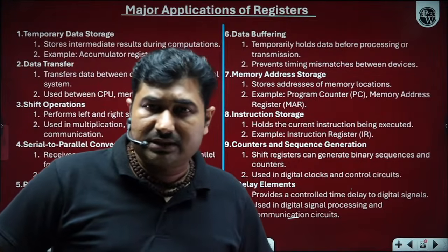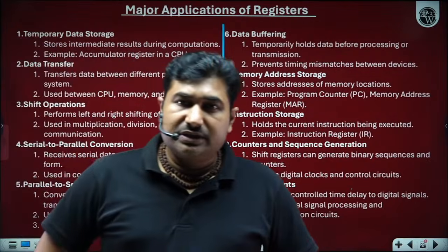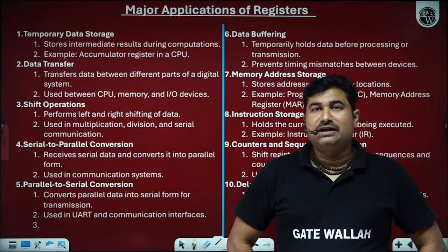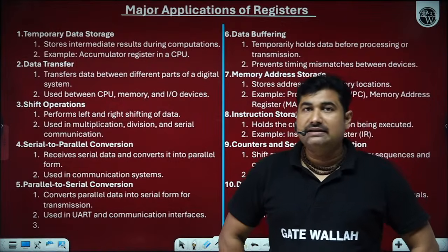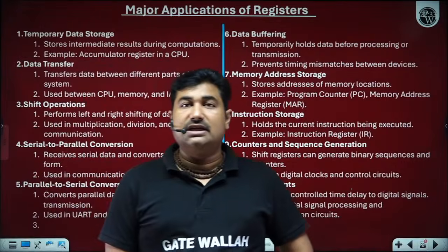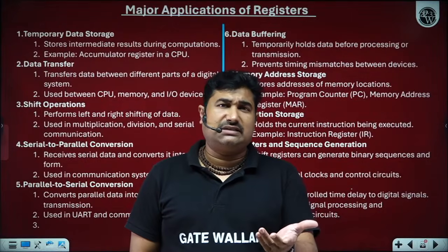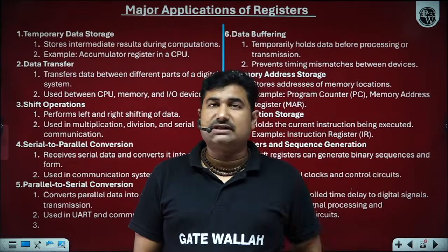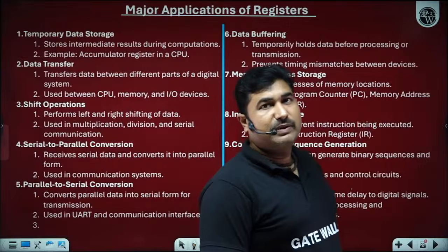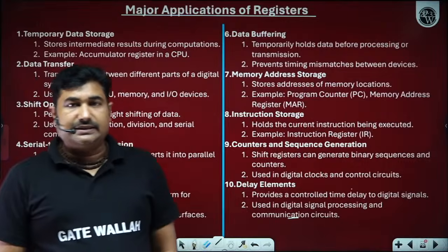PIPO is a register, only stores the data, no shifting. Why is it included under the families of shift registers in many textbooks? Betaji, actually the name is given as a shift register, and that is why in many different exams the question asks which of the following is not a shift register? So you can now easily understand why it is not acting as a shift register, because there is no connection of the inputs and outputs where the shift operation can be performed. Is it okay? Great.